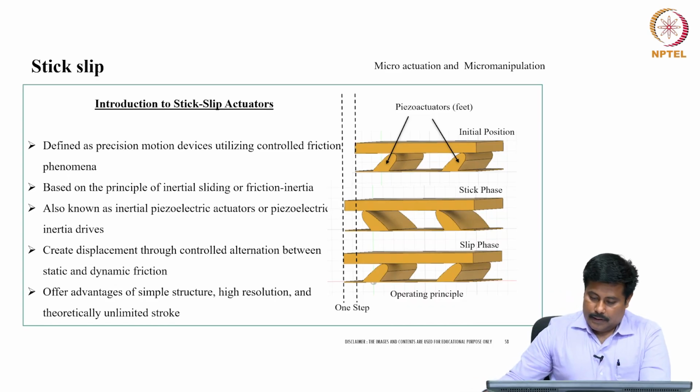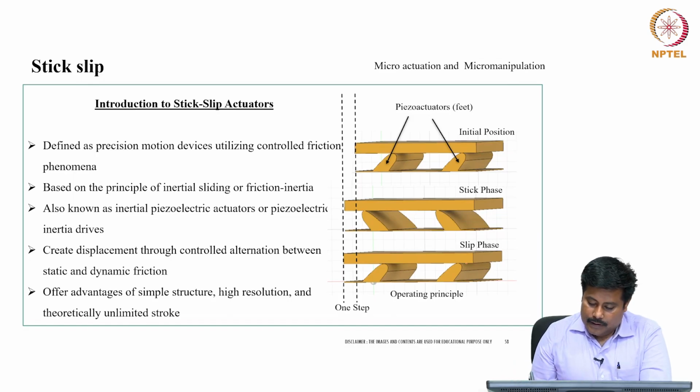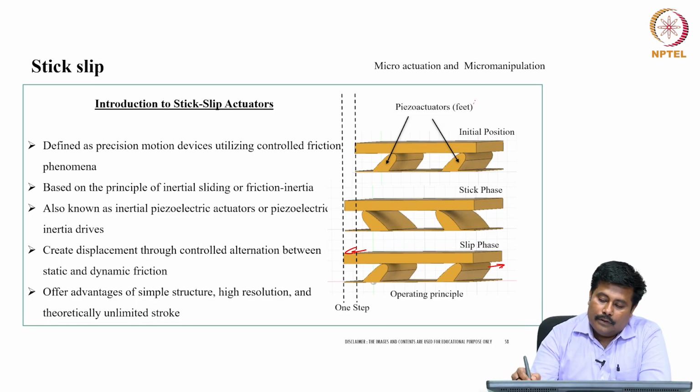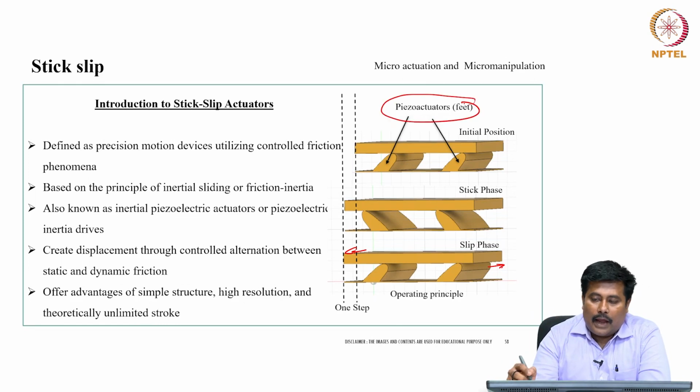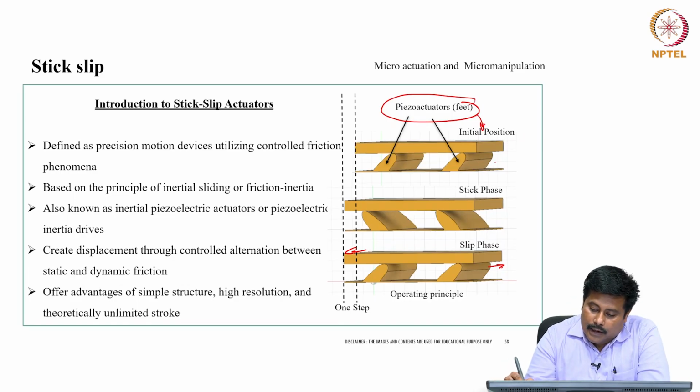In this particular case, let us consider this as an initial portion where there is a stick phase, and then from the stick phase, through an inertial force, it slips to the next level, so that we have a displacement. The generation of this stick phase to the slip phase is happening because of the piezoelectric actuation which is being deployed here.